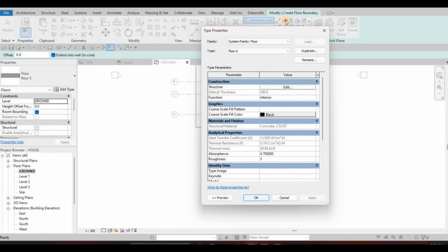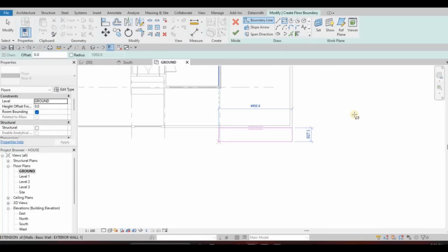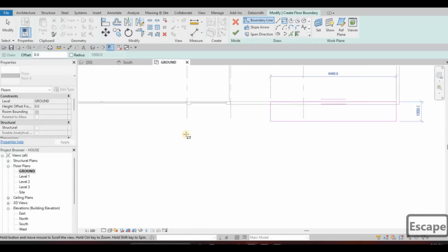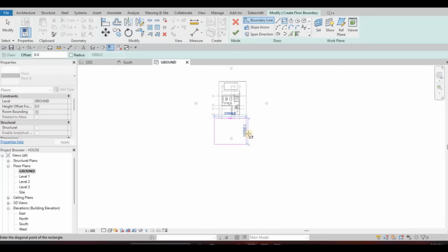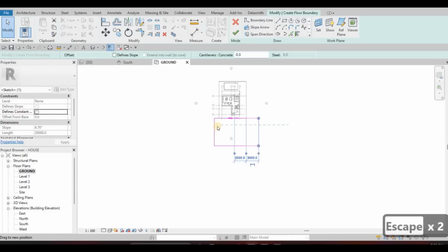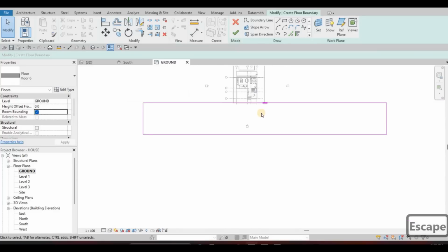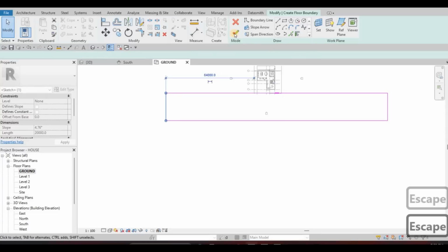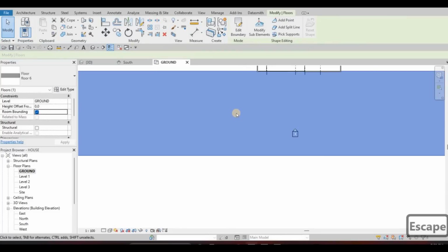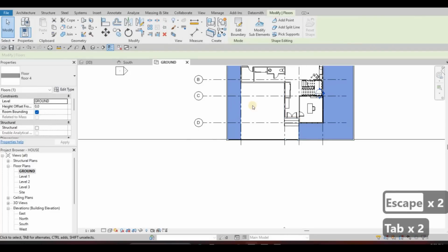And then we could just add concrete right here. We can put it all the way here so that everything's lining up. And then we're just going to do it at 20 millimeters. I think that's more than enough. I want to add in some grass part in front, like I said, before the sidewalk. So I'm gonna do that. I'm gonna add floor 6 right there. And then I want to add floor 4, which is the grass.